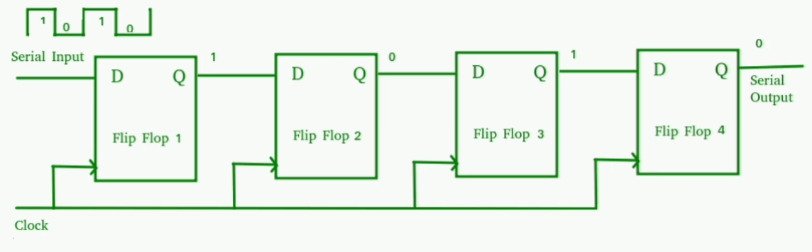Inverted ladder R-2R type DAC. For an n-bit DAC, V0 = (Vreference/2^n) × Σ (i = 0 to n−1) 2^i Bi × (−RF/R). So the current IF = (Vreference/2^n) × Σ (i = 0 to n−1) 2^i Bi × (1/R).